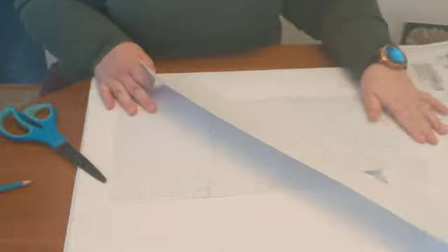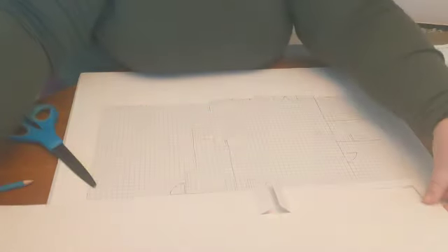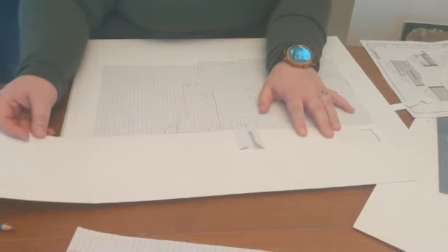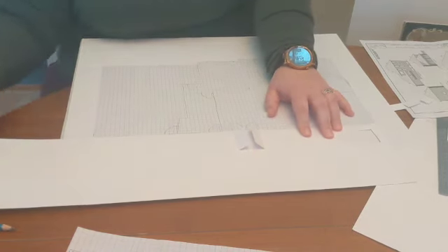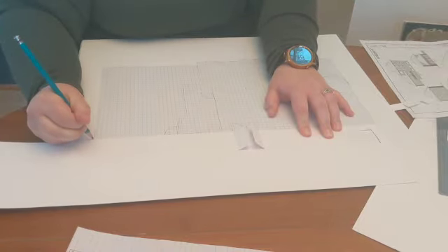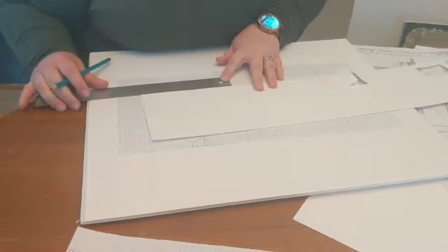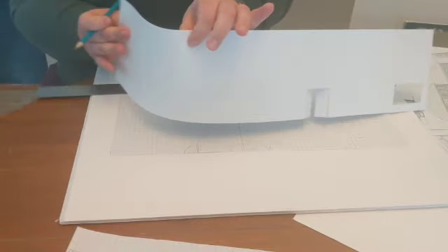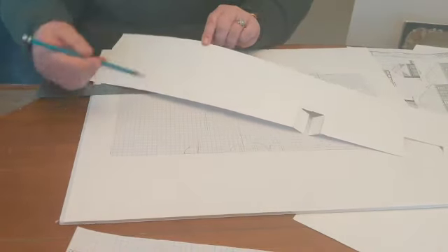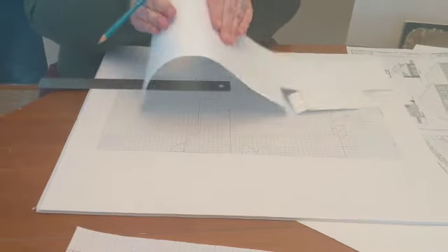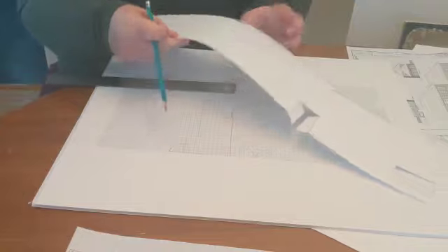When you're ready to actually stand it up and attach it, what you're going to need to do is line it up here and mark where your wall changes direction. I'm measuring and using a straight edge for this part so that I can make sure that I have a straight line that's even so that it stands up straight. Now, because it needs to bend this way, I'm actually going to draw my line on the outside because that's where my scoring needs to be. Your scoring will always be on the outside of the bend so that it kind of creates that area.